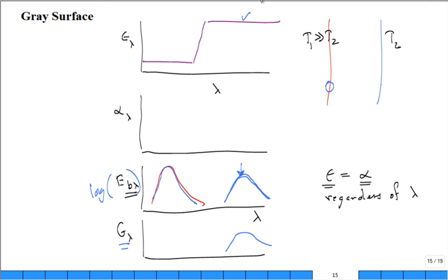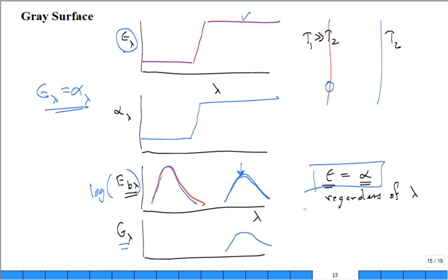So when you have dramatically different temperatures and you have a variation in the spectral emissivity, and the spectral absorptivity truly is the same, because Kirchhoff's law gives us that the emissivity at that wavelength is equal to the absorptivity at that wavelength, then you've got to be careful. If you jump from here, which is true, to here, that is regardless of the wavelengths, but the wavelength for the emission is short, and the wavelength for absorption is long. And so it's not true in that case for the average value.